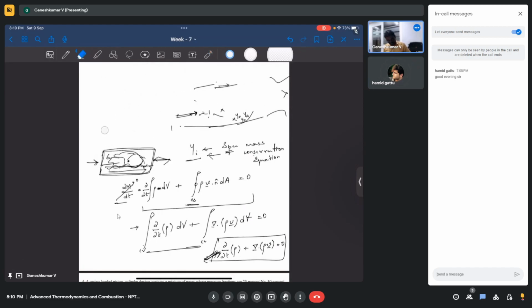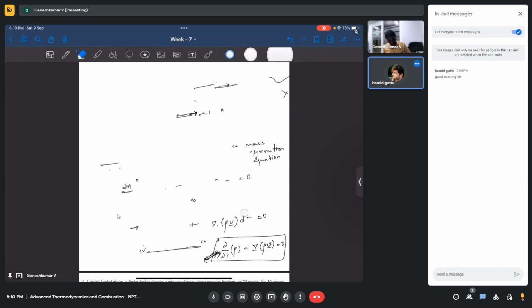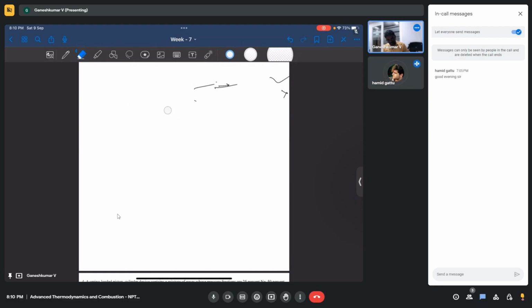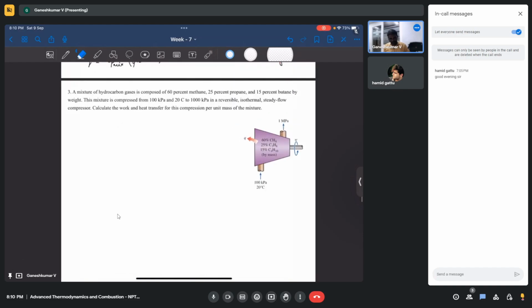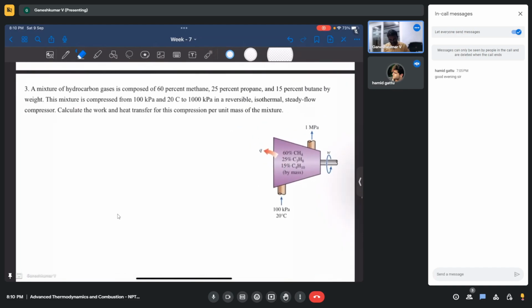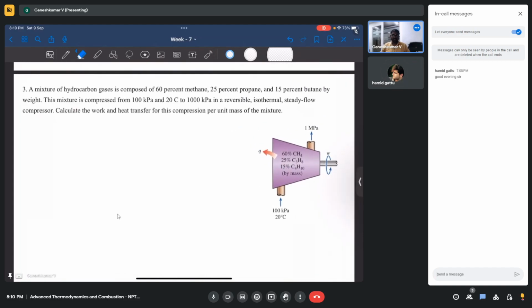Sir, I think we can say a similar thing for a diesel engine as well. In a diesel engine, until it enters inside, it will be pure air, right? And then you inject the fuel. So you will assume it's uniform, and you can do some simplified analysis, and you can get some performance out of it. But that performance would be more than the actual performance.